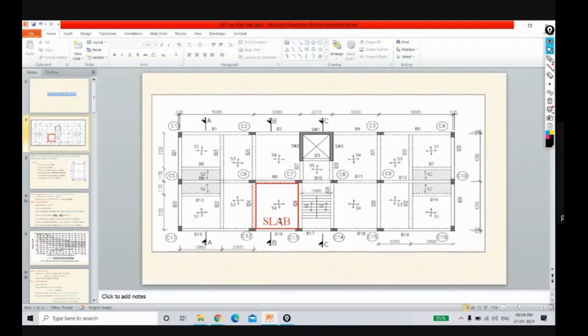Yeah, because I think I have one case at Mauda where the slab failed. At that time, the design had been checked. So that's why I'm having that question. Yes, definitely. First thing we have to decide, first we have to focus on the design. Maybe if deflection or cracks are there, reinforcement may not be provided sufficiently. But we cannot blame the reinforcement only. Because of concrete, at that time only the report will say what exactly is there. Correct.